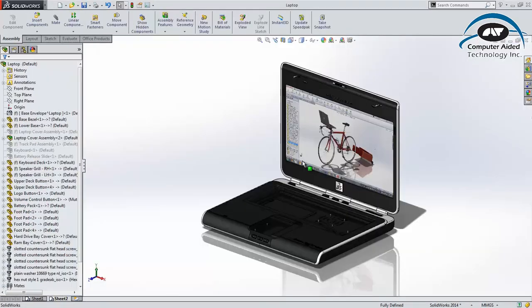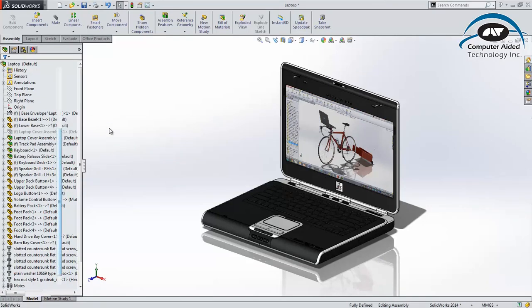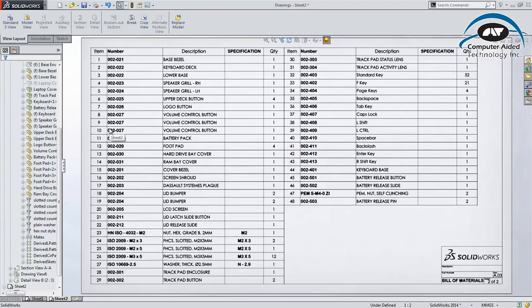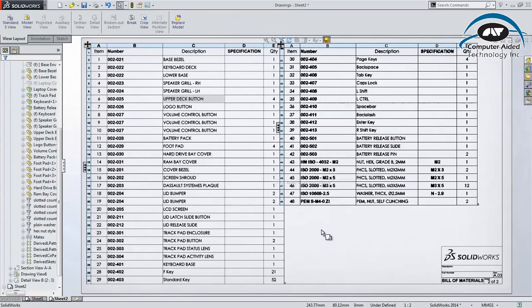table will be placed. When we add several new components to the assembly, referenced in the drawing, in the past we would have to have made these changes reactively. However, in SolidWorks 2014, when we return to the drawing, we can see that by previously setting the row count to split at, we've proactively avoided unnecessary cleanup, and the drawing looks great as well.